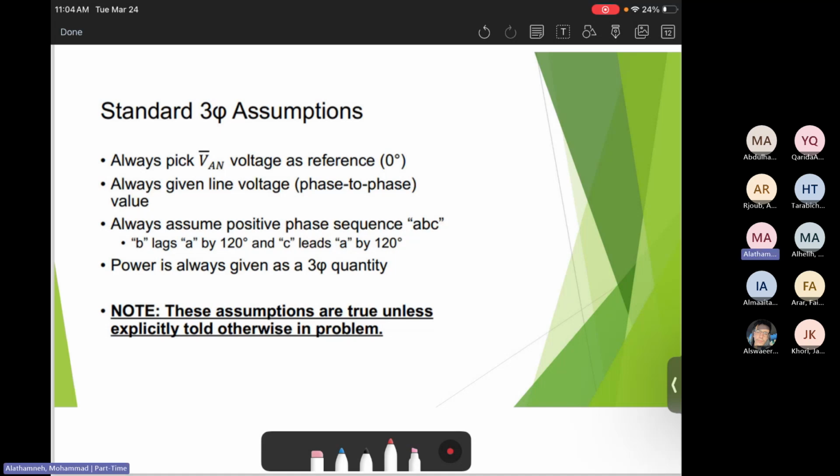to neutral. The other thing, every time assume a positive sequence, every time with ABC, and every time assume the positive, this is with 0, negative 120 degrees, this is with positive 120 degrees. That's what we will assume every time.